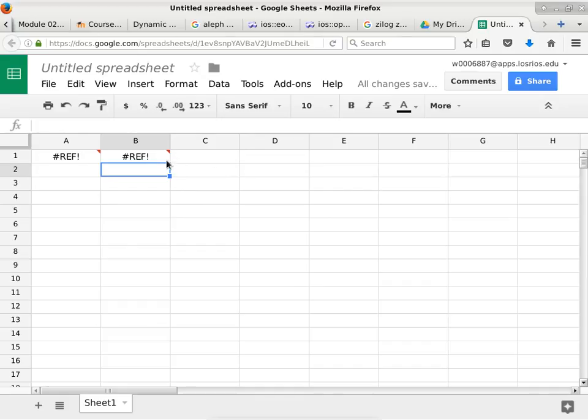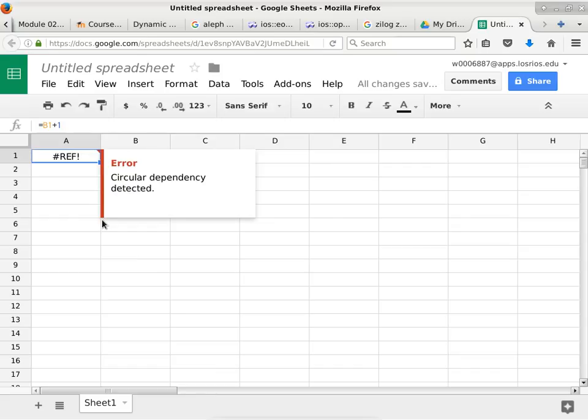So it's kind of the same thing, because even though we know that they're just oscillating between the value next to it and then the value back, and a blank is basically a 0, we should be able to see both of these things oscillating between 0 and 1, or -1 and 0, depending on which one is computed first. But the software refuses to do it because it now detects a circular dependency. And I think that's how Logisim works as well.